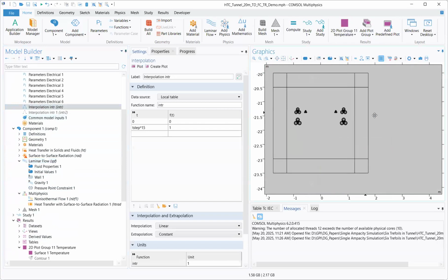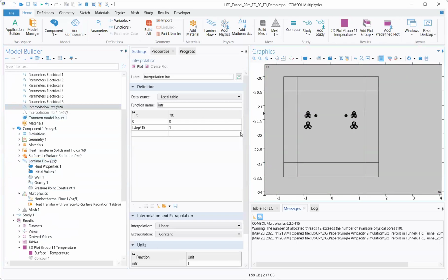But in this case, I got all these cables that need to initiate and start. Because they start at the same time, they have different requirements to satisfy the initial condition, right? The way the solver is going to solve it, the cables have different positions and different locations. So it's very hard to start the simulation without a ramp function. If we just put the full load of the initial heat, it's going to be very hard to converge. So I use this ramp function.